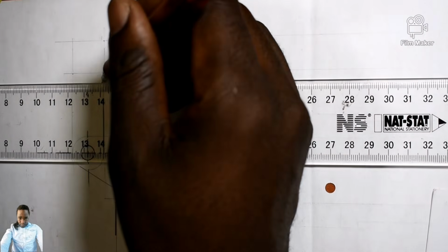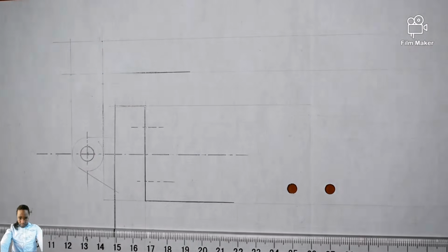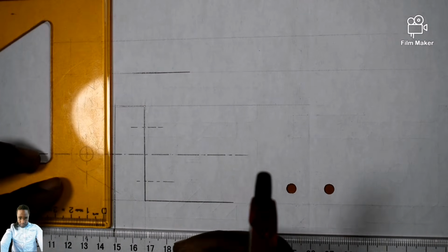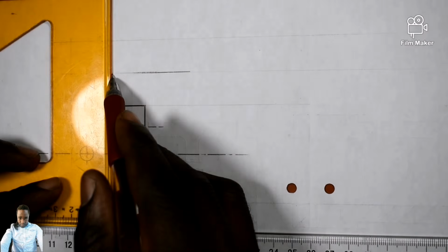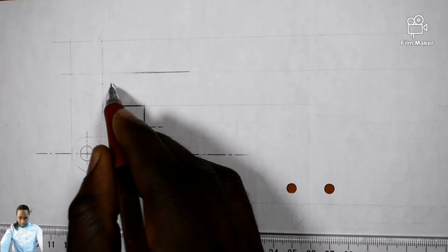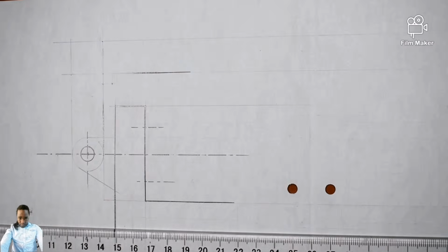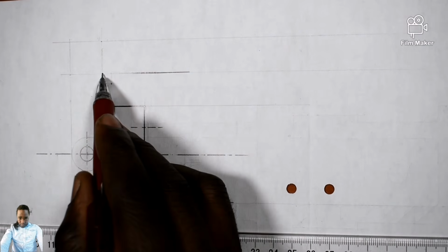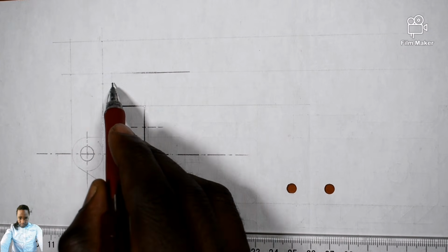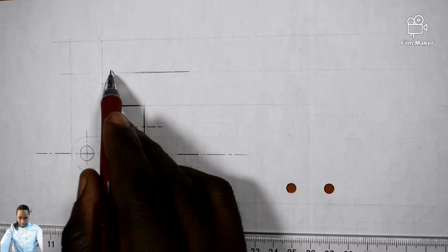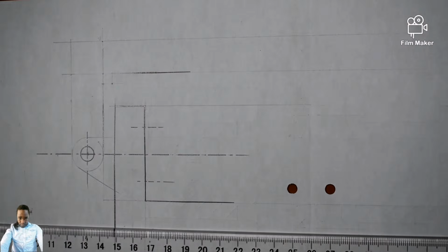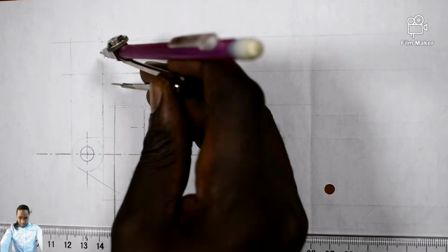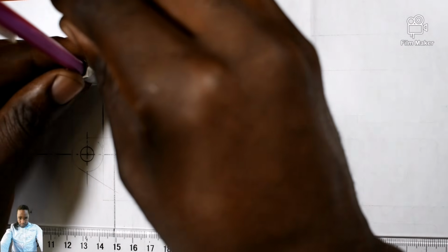So okay, now I can take this one horizontally faint and take this point that I just got vertically faint, so where they are perpendicular to each other, that's where I'm going to place my drawing compass. You understand? So from here till there is 5 millimeter, from here till there is 5 millimeter. So project this one horizontally, this one vertically, where they are perpendicular to each other. That's where you place your drawing compass and get this arc.